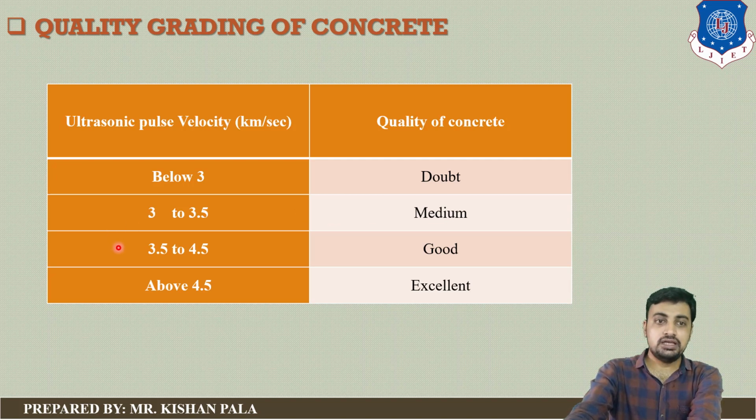Between 3.5 to 4.5 km per second, the quality of concrete is good. If your ultrasonic pulse velocity is above 4.5, the quality of concrete is excellent.